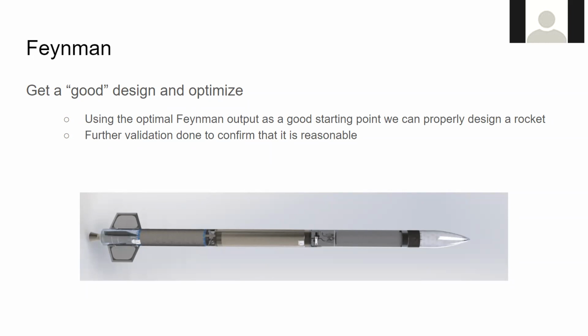You want an epoxy to hold the carbon fiber together, and getting the right proportions is difficult, so you buy it in the right proportions to begin with. We roll it up over a cylinder, generally 4 to 5 layers of carbon fiber. The end caps we make in a mold, with a similar process. Then we slip the end caps inside the tube and epoxy them in place.